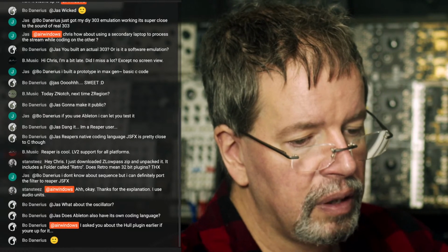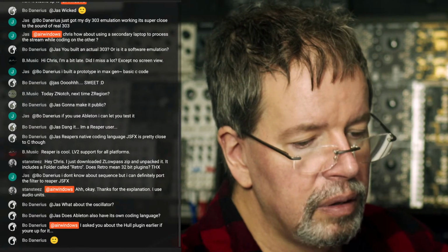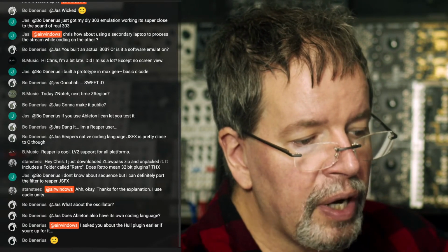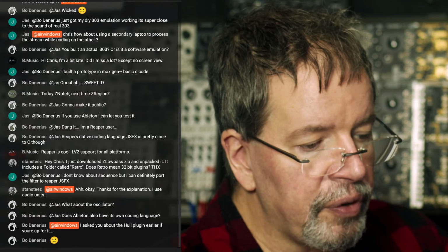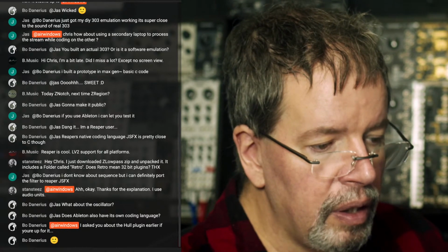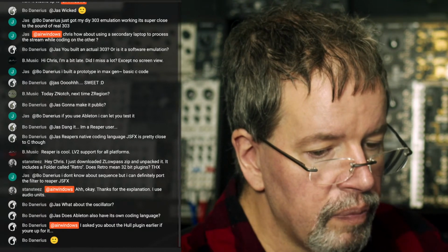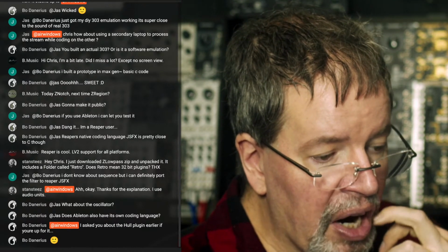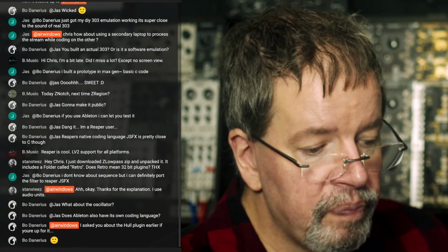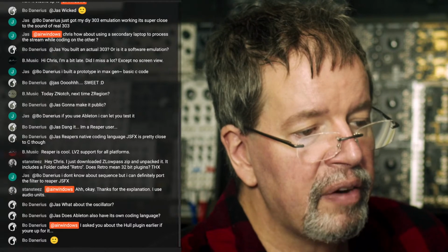Let's see now. I see the way in which the notch filter looks different from the other filter. I've got my biquad A handy here. And these are the bits that I would be changing. So I'm having an eye to see whether I spot anything else that I would need to change, but I think that was about it. I'll close ZNotch after having taken that out of it.